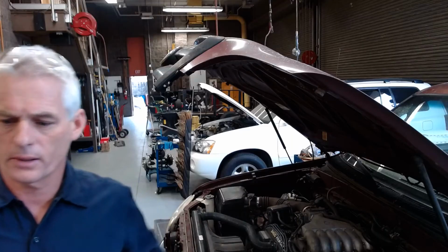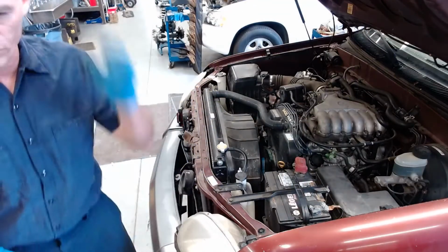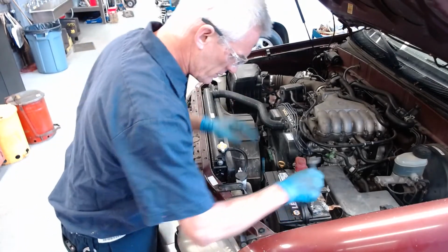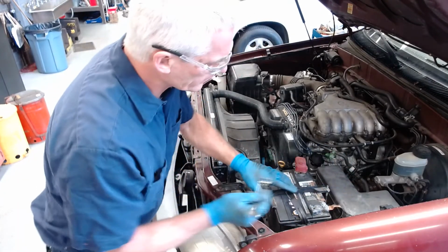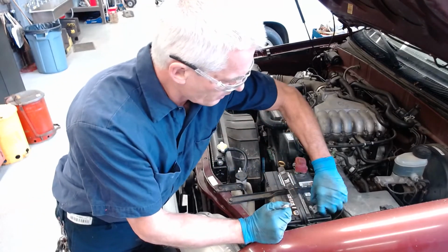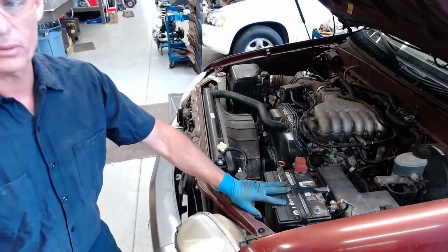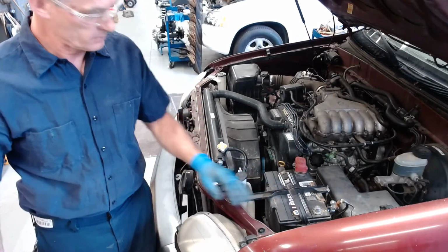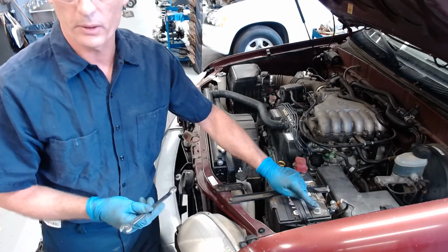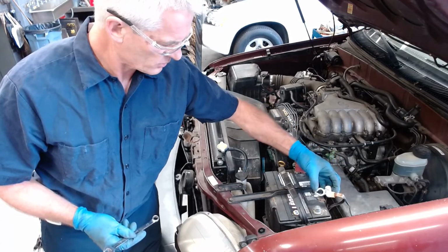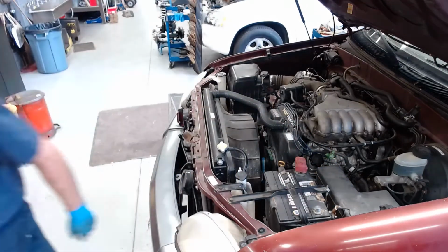We're going to give a brief video on removing a starter motor. And the first thing we're doing is, on this '04 Tundra, put our safety glasses on. We're going to go ahead and take the negative battery cable off, and that's always our first concern, because we don't want to touch the positive lead where it attaches on the starter and get an arc. This, of course, clears computer memory, so you have to rerun monitors if you have to pass them. Normally, it's a 10 millimeter on a Toyota, but because I've got an aftermarket clamp here, this is a 1/2 inch size right there. So the battery's disconnected.